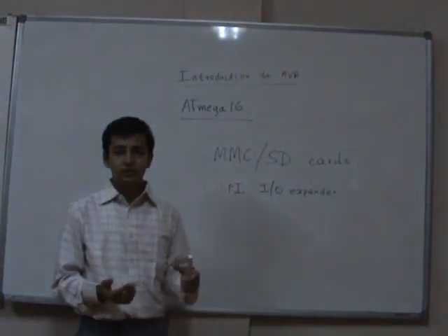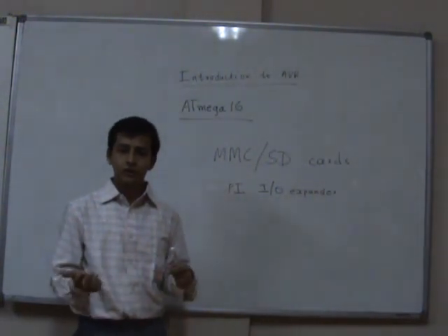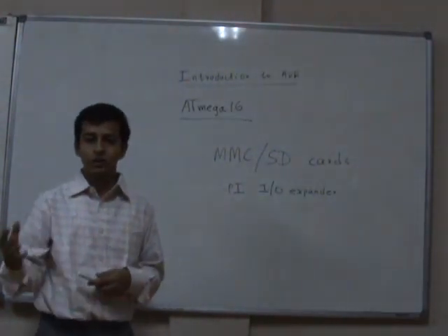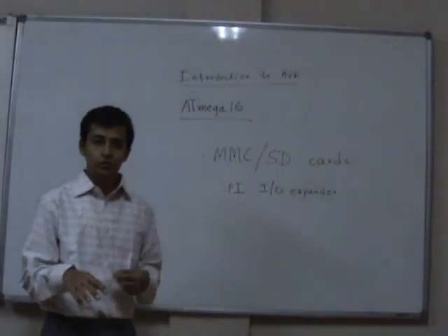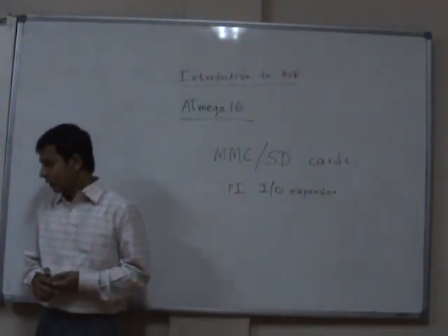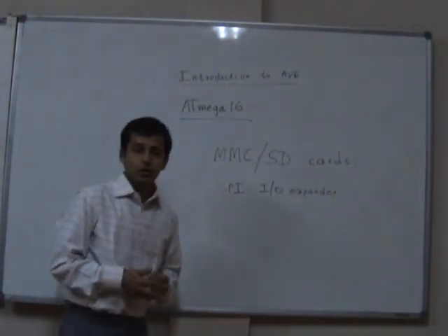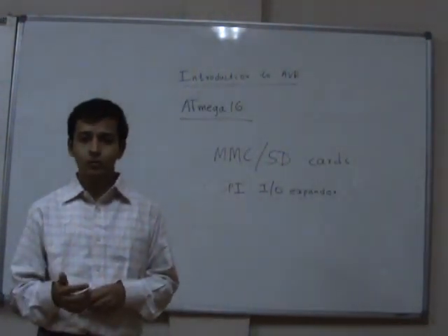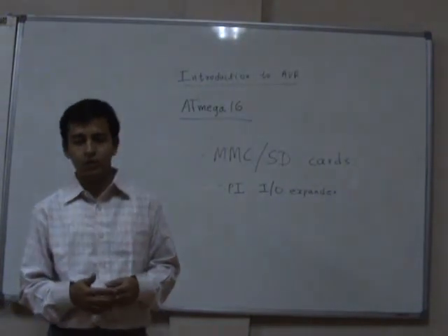It is basically a chip which communicates to the microcontroller with the SPI protocol, and it gives you the additional 16 or 32 input outputs, which you can use for controlling different devices. Then it is also having support for the I2C protocol on chip. With that you can interface I2C EEPROM or any other device which uses the I2C bus.